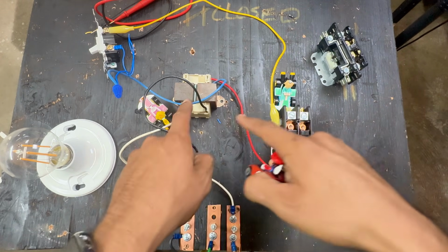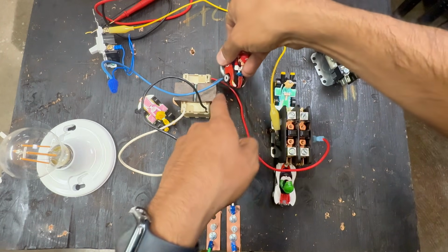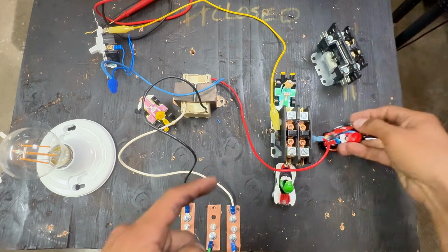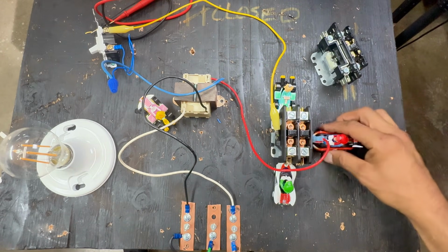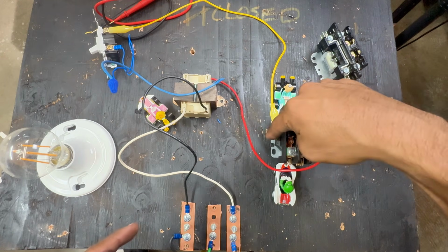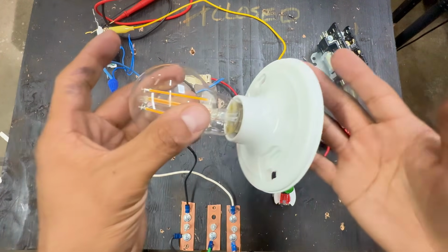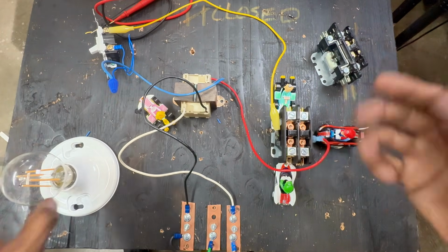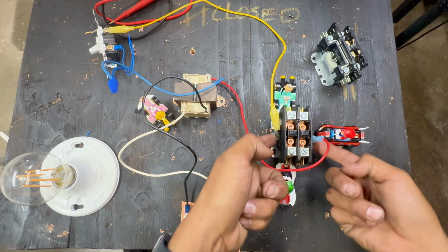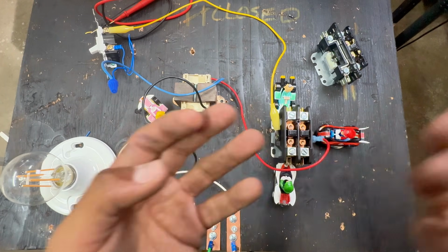Follow Mario. If we follow the 24-volt source, you see there's nothing interrupting Mario. He's already here. He's like, all right, Peach, I'm ready. Come on. And Peach has to make it to that side of the coil of the load, because that coil is a load just like a light bulb. It takes power. The coil is not a switch. This is a switch, but not the coil. It needs power. It needs a hot and a common.